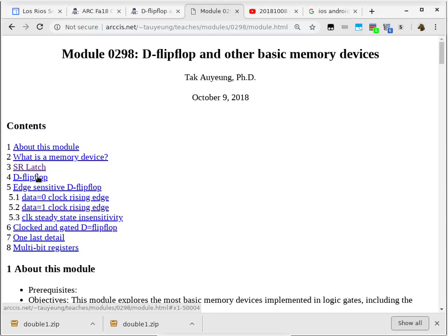But you don't want to transition from 0, 0 as inputs. Excuse me, you don't want to transition from both inputs being zeros to both inputs being 1s, because that will make the SR latch enter an oscillation state, which is usually not intended and is not good. All right? So the next concept is a D flip-flop.